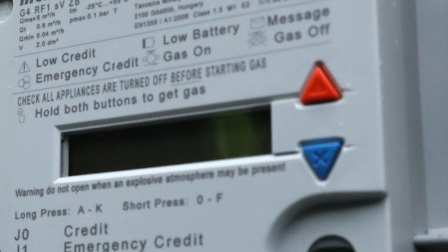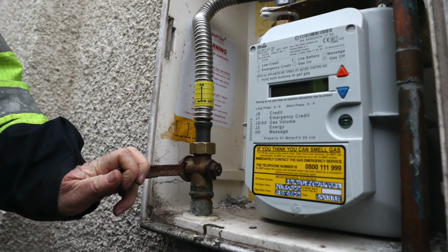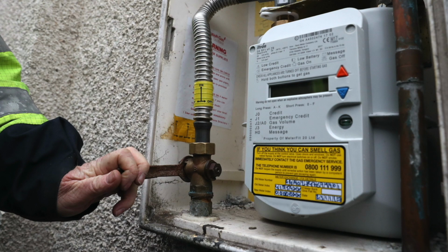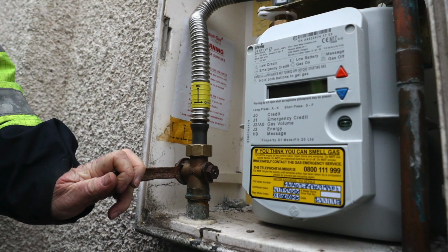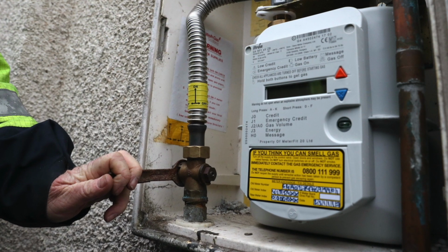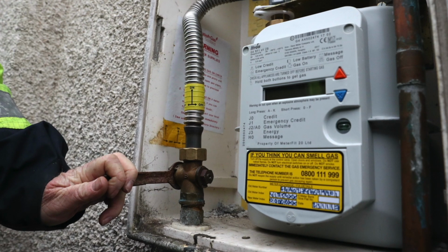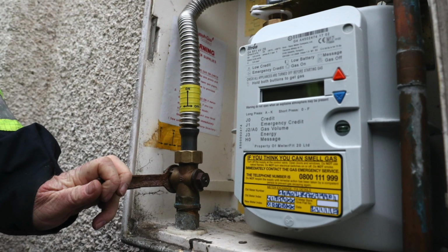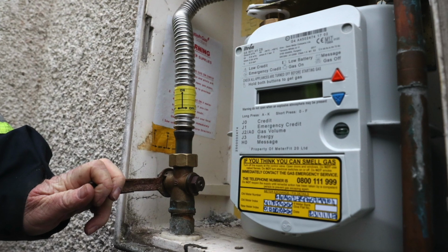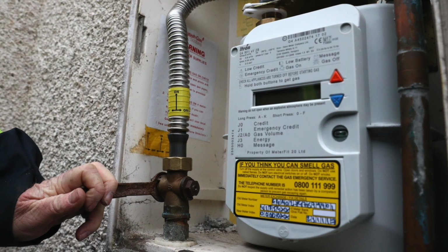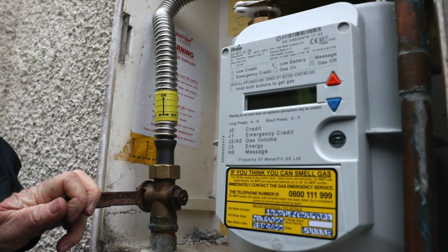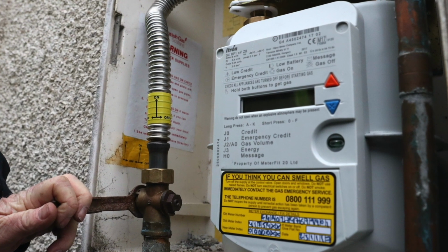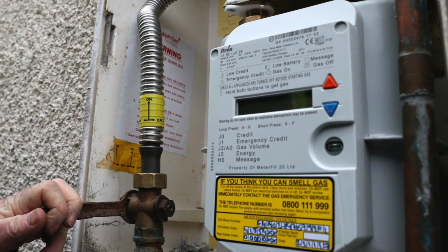The meter will wake up and start to show the index with the gas flow on the screen with an AO. If the AO is not displayed on the screen, then you need to scroll through by short pressing the orange triangle button. So within 30 seconds of waking up the meter, at the next increment on the index, we need to start the stopwatch and take the first reading. And then we need to do our 2-minute test.